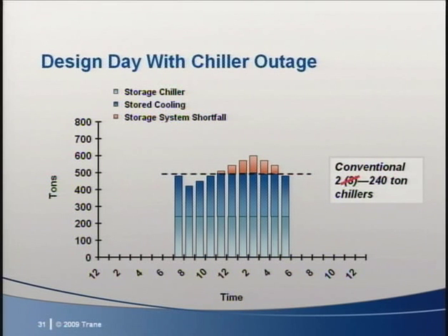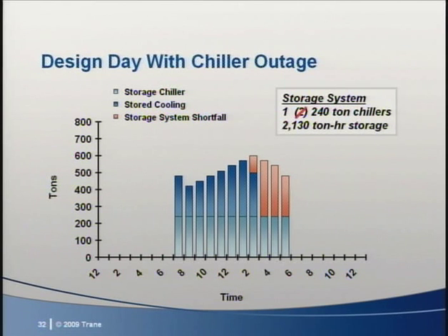One myth is that ice storage systems have less redundancy. Let's look at what happens during an equipment failure. If you have 3 chillers and one's unavailable, or if ice is unavailable, you'll be short cooling in 6 of 11 hours, shown in red. If a chiller is down but you have storage available, the remaining chiller and storage would be short capacity for only 4 of 11 hours. Or you could use the ice more slowly and have a similar situation to an offline chiller. For true N+1 redundancy, both systems would need 300-ton chillers, 3 for the conventional and 2 for the partial storage system. Any off-peak cooling system can meet the same redundancy criteria as a conventional system at a comparable cost.